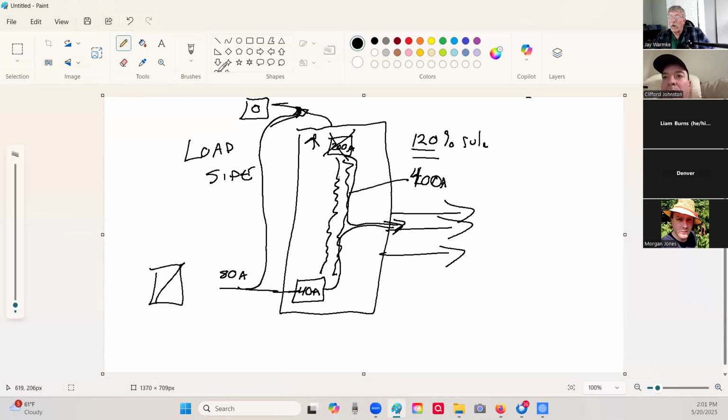But it's more and more unusual to find a service panel that has enough capacity and enough open spots to make that connection. Often if you're out there in the field, these service panels are just chock-a-block full, and maybe they were installed in 1970 and it's all crappy. So we'll come up with a different option. I'll give you a preview.